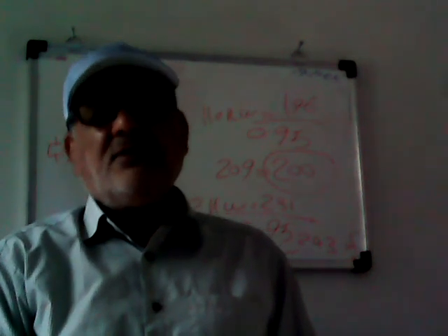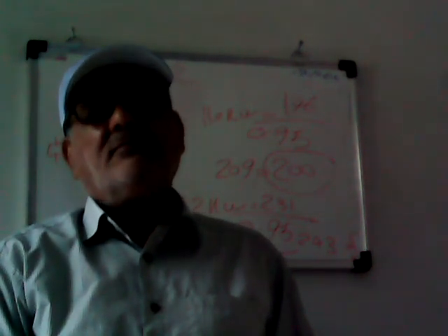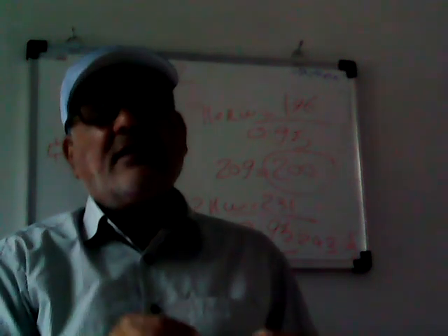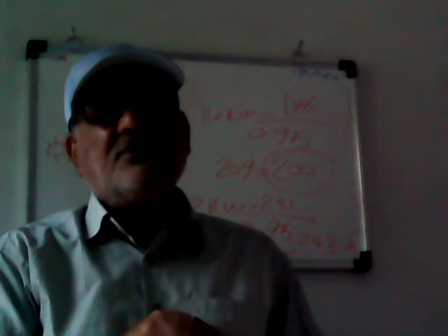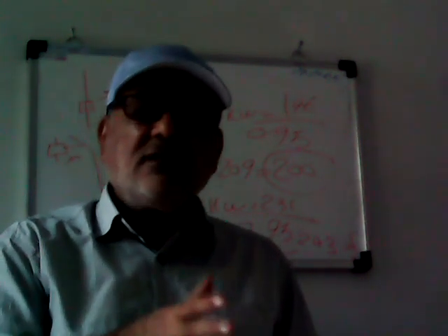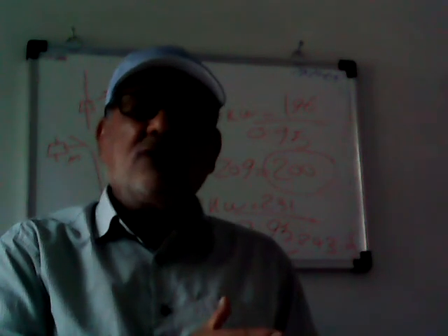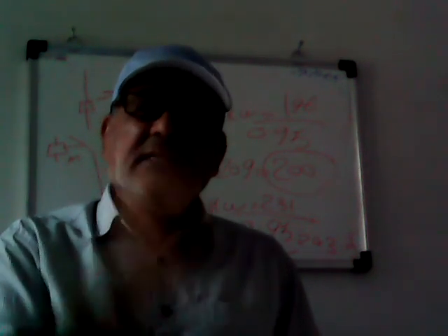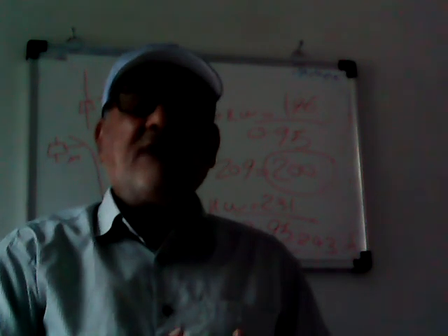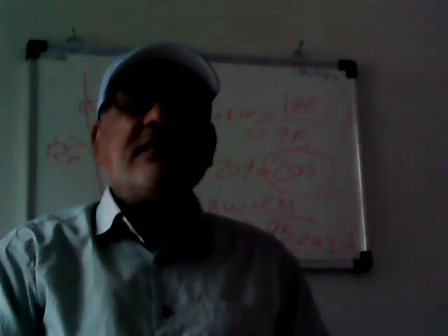You directly use fuses in soft starter and drive equal to the rated nameplate current or close to that. Or if you want more protection, go one step more.